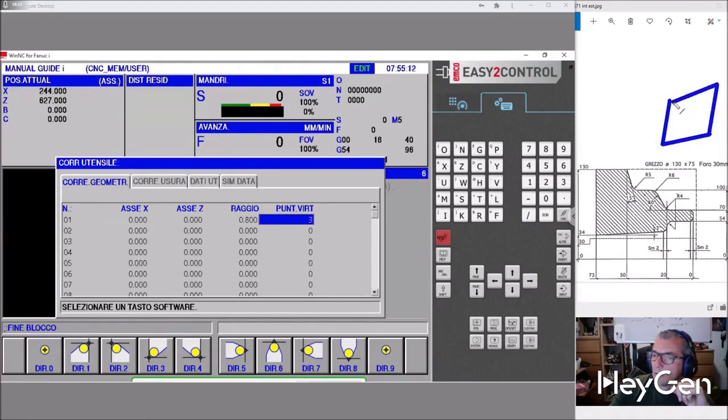Now this part is only for the graphics. We're going to say we're using an external general tool positioned according to the little drawing we see, a 95-degree approach angle and an 80-degree insert angle. Perfect. Now it can calculate the graphics. At this point, let's enter M4, S200, G96 and EOB insert, so the cutting data, where we will position ourselves quickly. First of all, G00, X300, Z0.